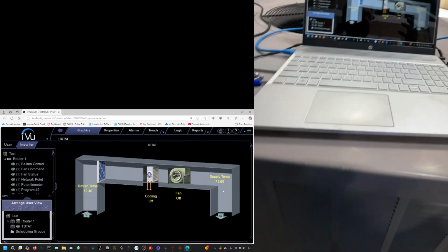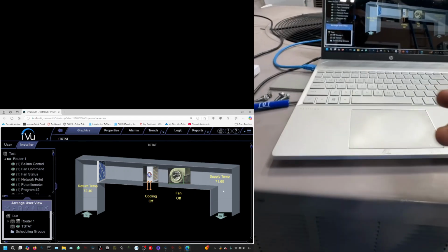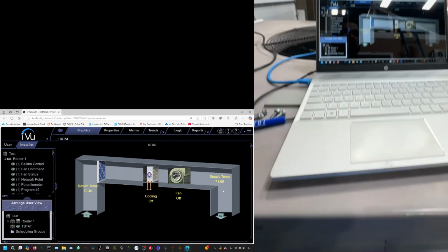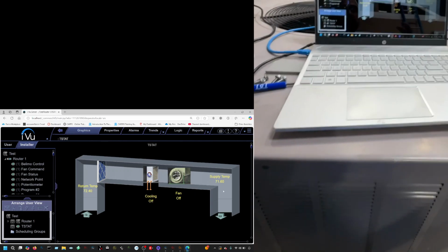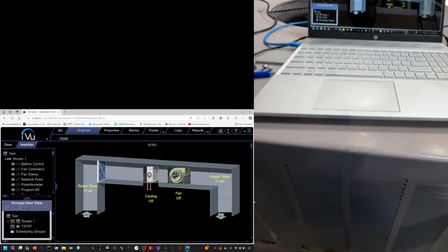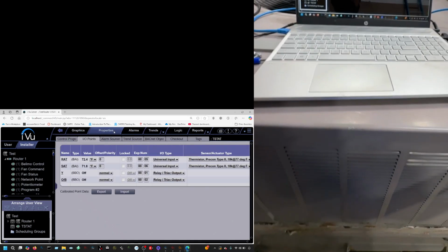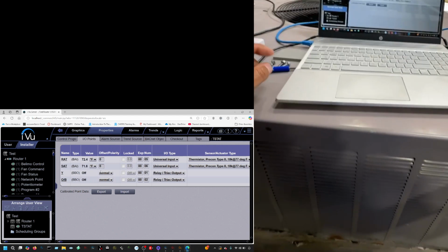Yes, compressors can definitely be low on charge, and you call for cooling and it's never cooling. Same temperature, return and supply. It's not dropping in temperature. So let's go ahead and do that. And I can confirm it right here once we send an on signal.